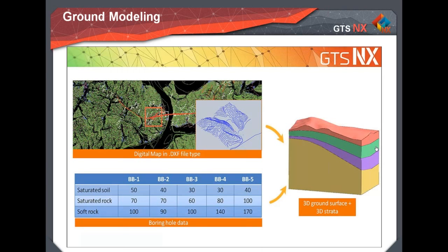Okay, so that's just the basic overview of the command system of the program. And then another great feature of the program is its advanced modeling features for complex geometry, specifically for grounds or for soil strata layers. So, for example, if you have maybe a 3D contour model that you want to import into the program and model, you can actually do that using the features that are available to you.